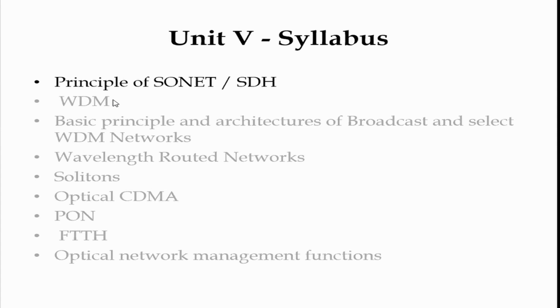Okay, so SONET and WDM are the standard multiplexing techniques through which multiple data can be condensed into one single branch and transmitted over a single fiber. So SONET, synchronous optical network, or synchronous digital hierarchy, are the methods available to multiplex multiple data into one branch.